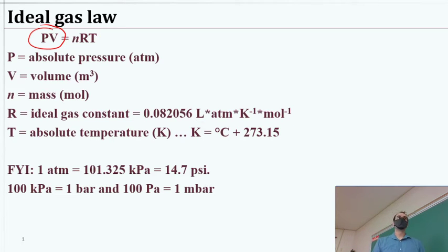Because if you've ever noticed, if you drive when it's very cold, your tire pressures might be a bit lower than you're expecting, and you might have a tire pressure sensor going off because the low temperature means that's a lower volume that air is occupying. Because if you reduce this side by reducing the temperature, then the pressure times the volume has to decrease. If your volume stayed the same, you have the same size tire, you have lower pressure, right? So there's a lot you can do with this relationship with the ideal gas law, and chances are you've seen that in action, just never quite knew it.